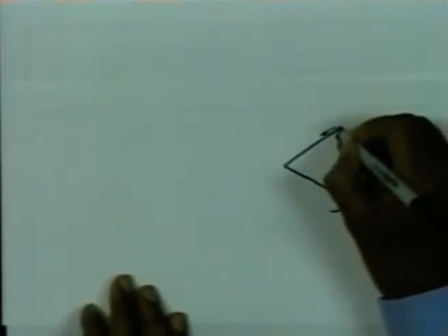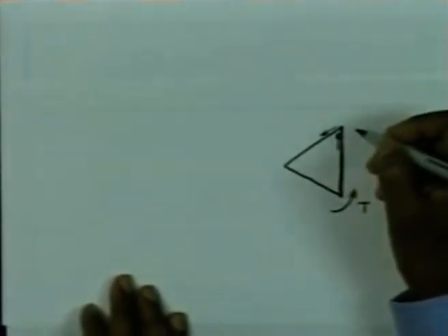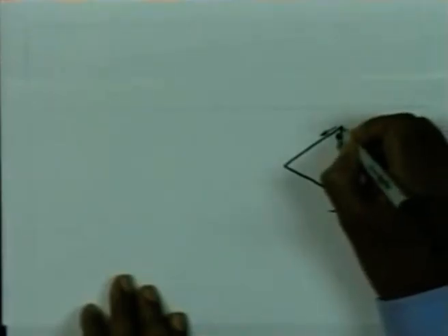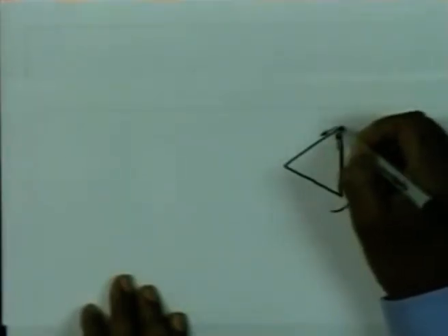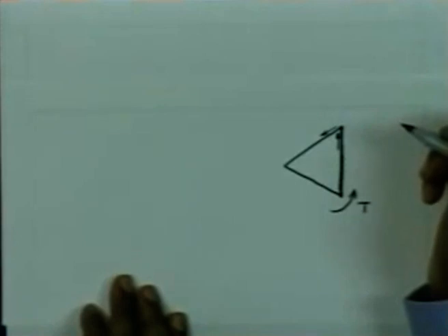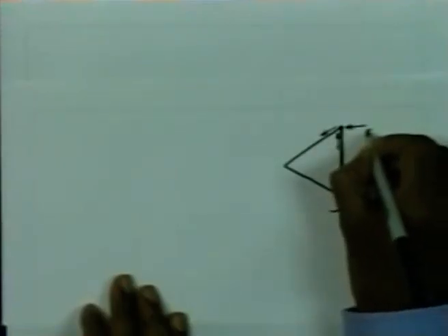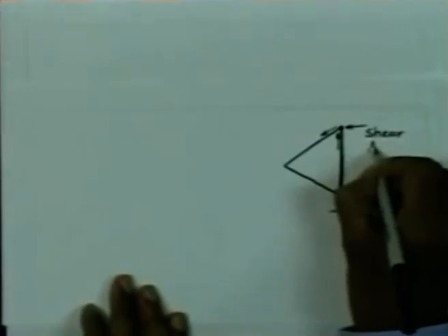Now, at this point it is a common point. So, the stress at this point is going to have duality in terms of direction. So, therefore, there cannot be duality of stresses at a corner point, and therefore, the stress at this corner is going to be 0. So, this cannot be a point with stress. So, shear stresses are 0 at this corner.